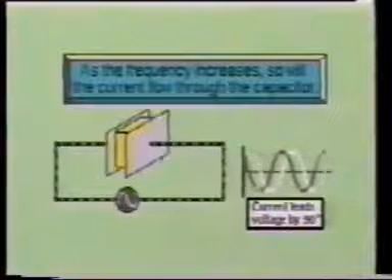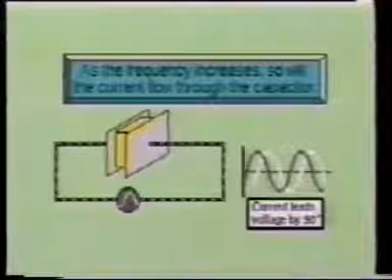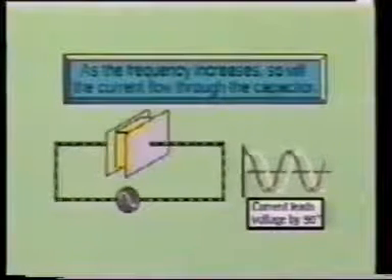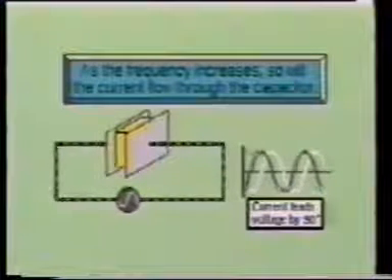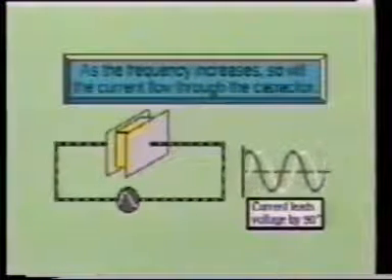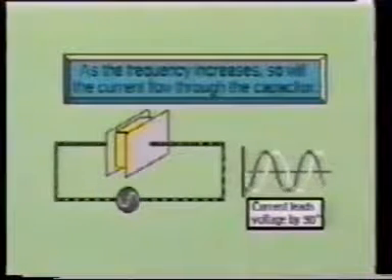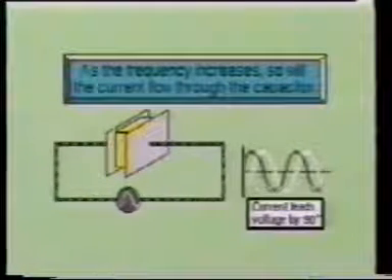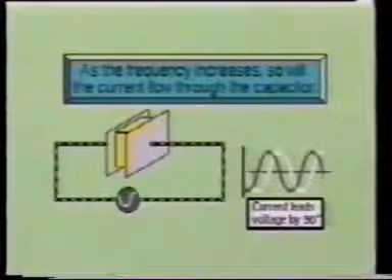The reason for this is because when the voltage is first applied to the capacitor, it will conduct a heavy current flow, but the voltage must take time to charge to its full potential. Also, when the charged capacitor is discharged, it will conduct another heavy current flow immediately, but the voltage will not drop as rapidly because it must take time to discharge. For this reason, a phase shift exists between the voltage and current of the capacitor.